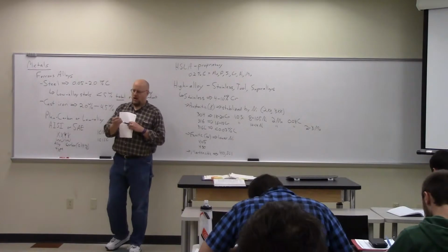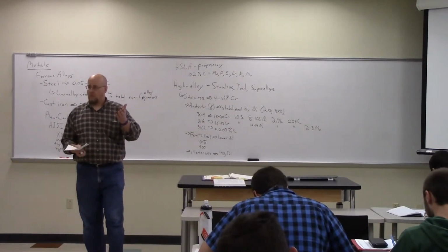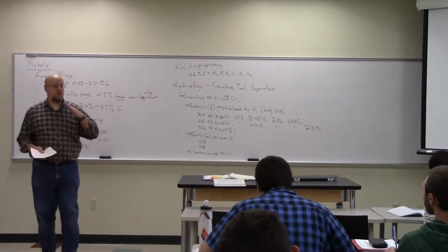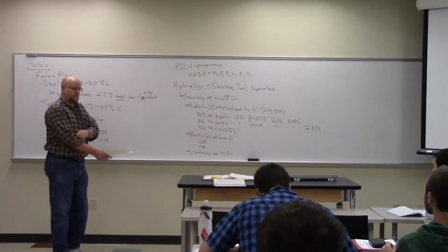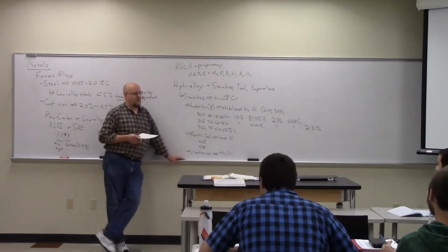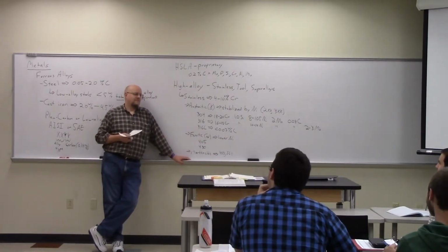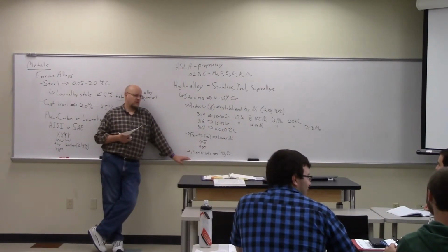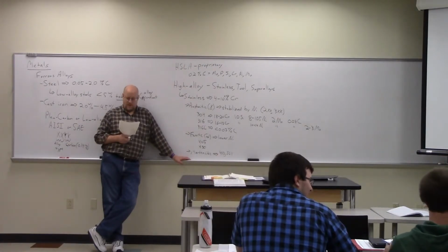So use that for your knives, your razors, your things that need to have a sharp edge. As I said before, martensite's a high strength material, so you want your edge to be sharp and stay sharp. You want to make it out of martensite. Like swords. Except really, you typically don't, a sword's not all just about the sharp edge. You don't want it to be brittle, you don't want it to just be hard, but anyway.